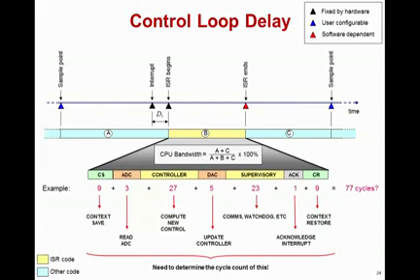Section B shows the actual interrupt service routine, or ISR code that's calculated. First, you have to context save the processor, read the ADC, calculate the new control code using the function we described earlier, update the controller, or in this case our PWM, do some supervisory tasks such as communicating or doing a watchdog reset or timer check or something to that effect, acknowledge the interrupt, and do a context restore. At this point, the ISR ends and you wait until the next sample point.